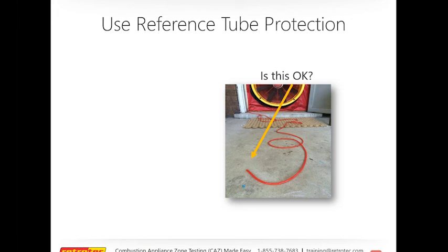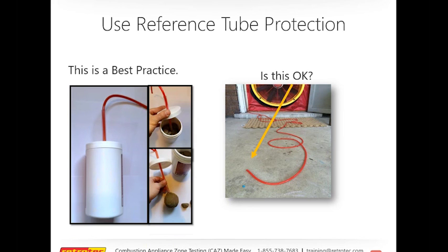In an inch of water column, if you take a straw and pull just an inch of liquid into that straw, that's almost 250 pascals. So these little bitty pressures are very, very sensitive. So it's so important that you make sure that your reference hose is safe and that it's not getting these wind-driven effects on it.